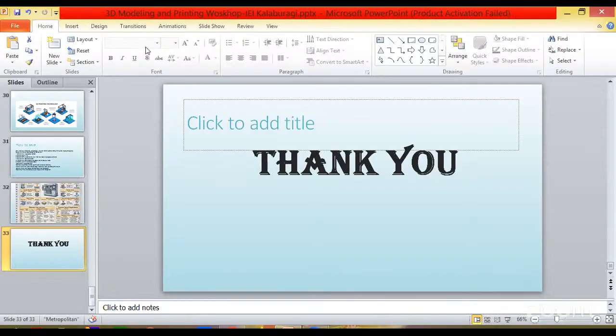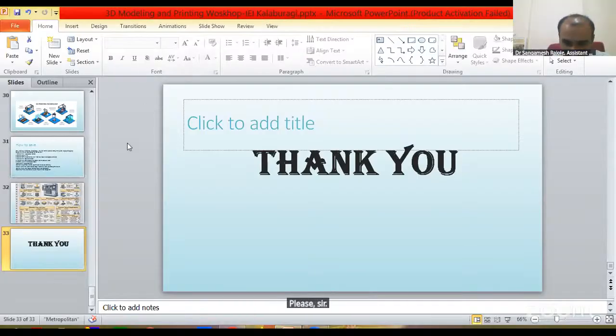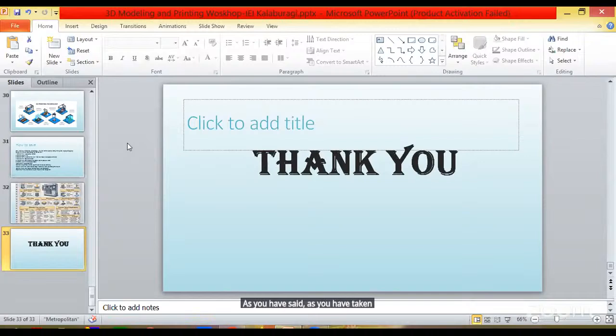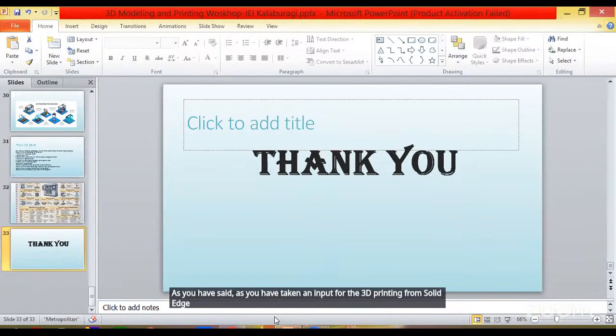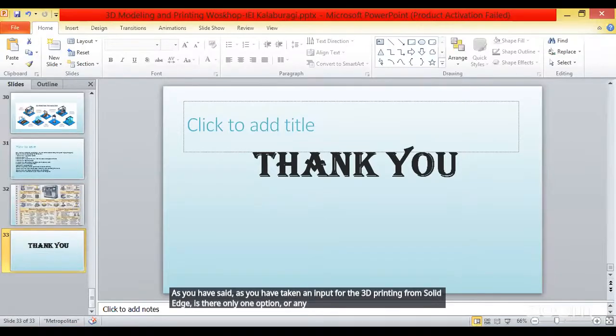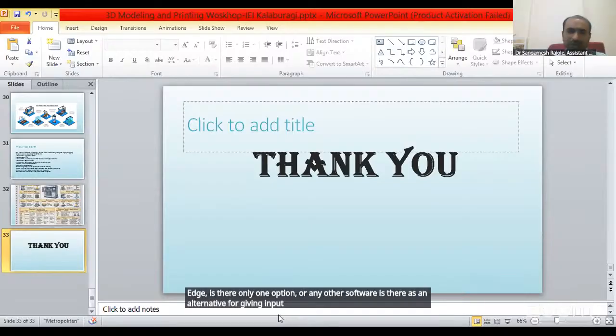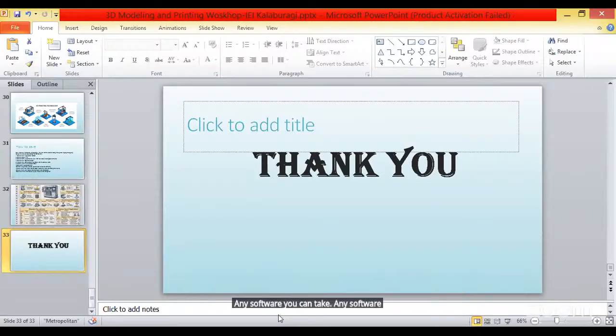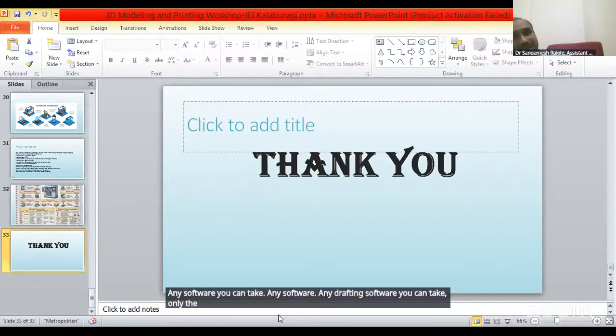Sir, there is a small question from my side also. Please, sir. As you have said, you took an input for the 3D printing from Solid Edge. Is there only one option, or is any other software an alternative for giving input? Any software you can take. Any drafting software, any CAD software you can take. The only criterion is you have to save it as an STL file.